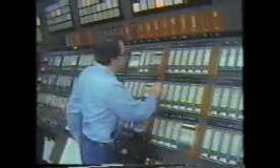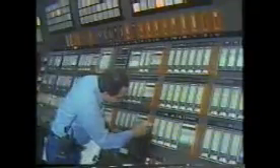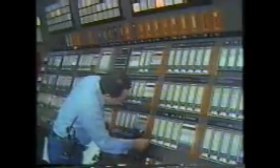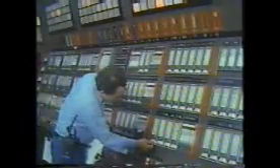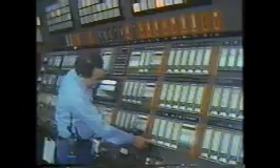Another problem might be the buildup of residue in the lines that carry either mixture or products. Such a buildup could block the lines. If this takes place, the blocked line will need to be cleaned out. Finally, one of the instruments used to monitor or control part of the distillation process could fail. This kind of problem may not be immediately obvious, but as operators gain experience with their systems, they learn what kind of readings they should expect. When an instrument reading seems unusual or wrong and everything else appears normal, maintenance should be called to thoroughly check out the instrument.